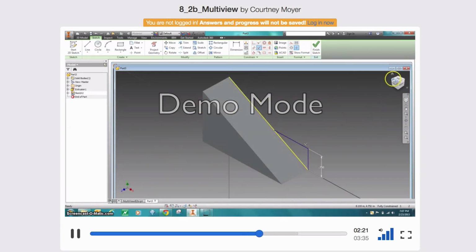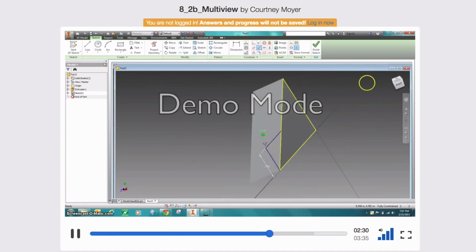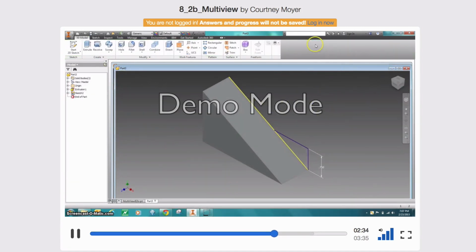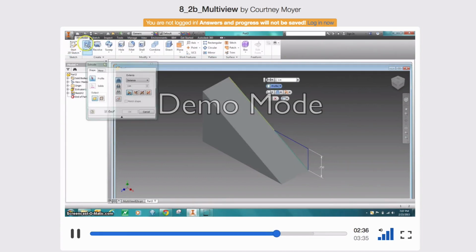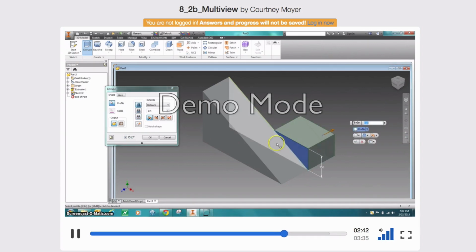Now what that's done, in my original view, is you can see this sketch from the back side. It's going to be flush with the back, which is what the plan calls for. But I am going to finish the sketch, and then I can extrude. Now, what I've learned so far with the extrusion is I have to select what I want. As you can see, that's going to go a whole inch.